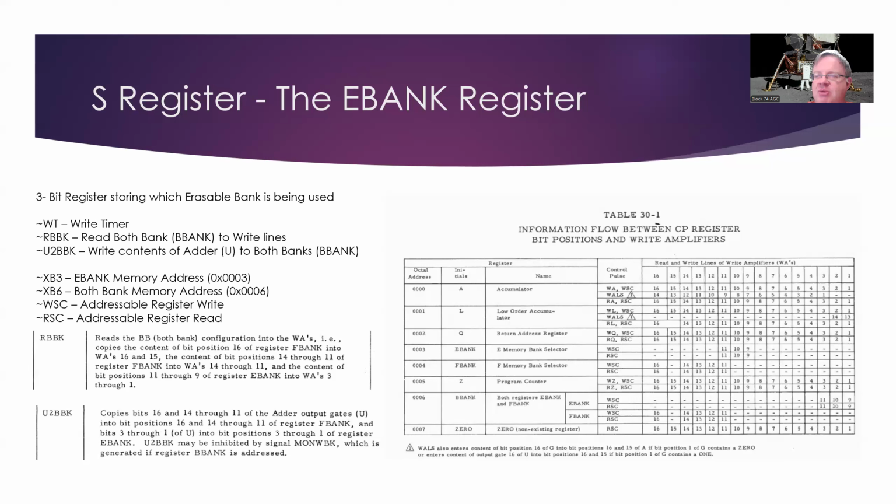It's pretty clear how we write data into the EBANK and the FBANK, but for the fixed extended bank, I was having a harder time finding where exactly that data comes from, and it actually comes from some of the I/O logic. I've found the documentation in the manual itself, I think it's I/O register 7, that brings in the contents of the extended register.